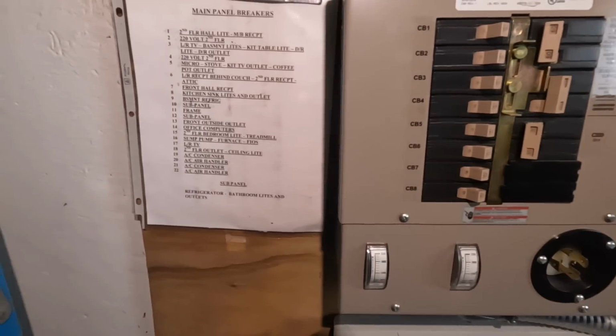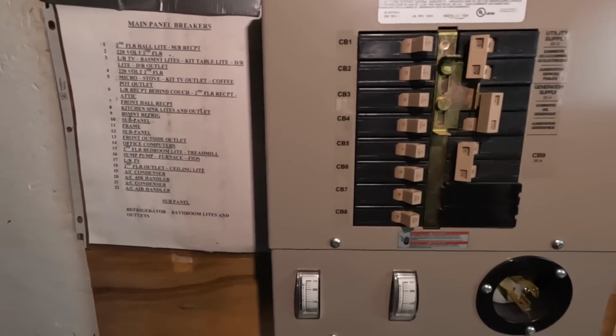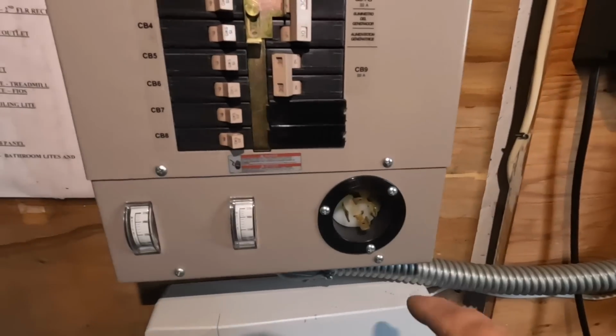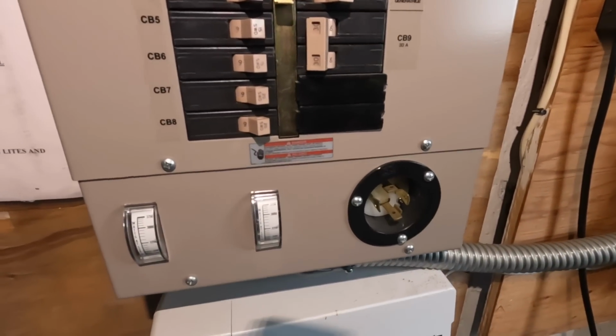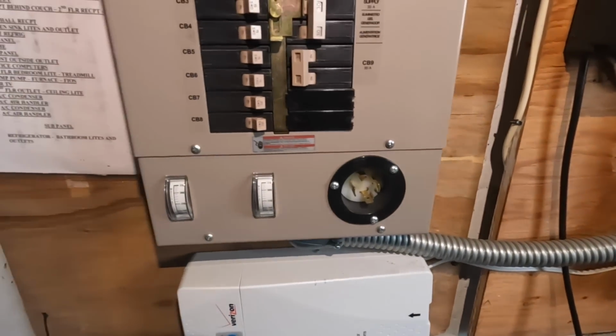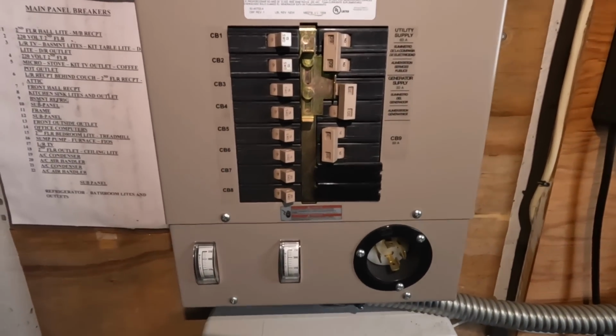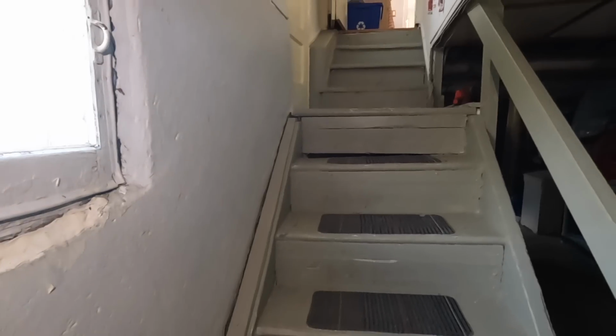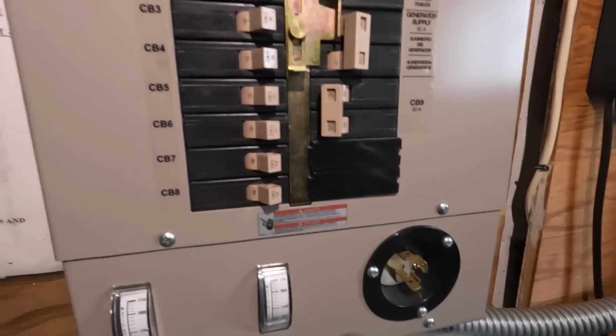And this is the system I put in. I checked this out. It's all wired correctly. It's not how I would have done it. I always like to have my inlet outside, so you wouldn't inadvertently start your generator inside, but you'd have to get the generator down these stairs, and I don't know if you can do that. I'm going to leave this in place as it is.